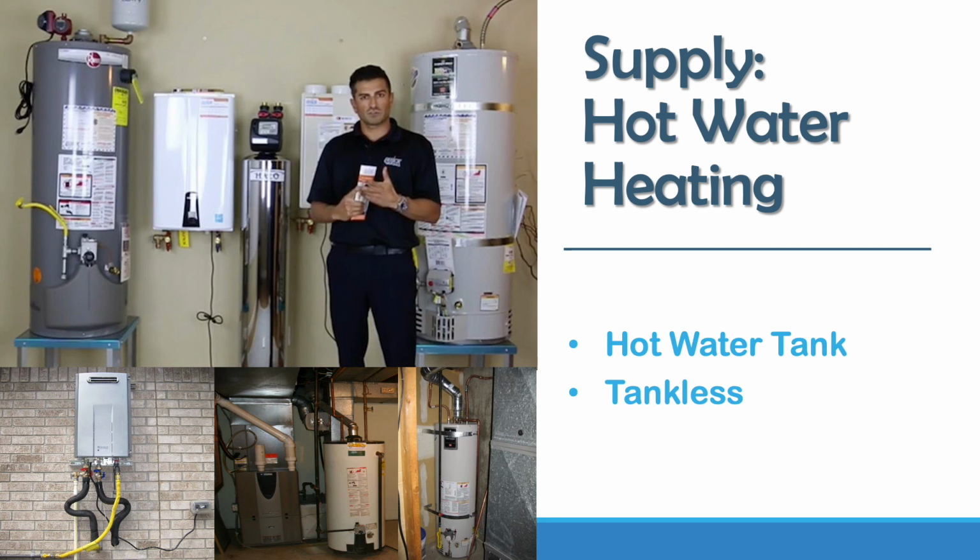And it is important to keep in mind what your gallons per minute of different fixtures might be, so that if you are setting up a tankless system, it's sized appropriately. The plumber can help you figure out a size, and knowing the gallons per minute is important too.